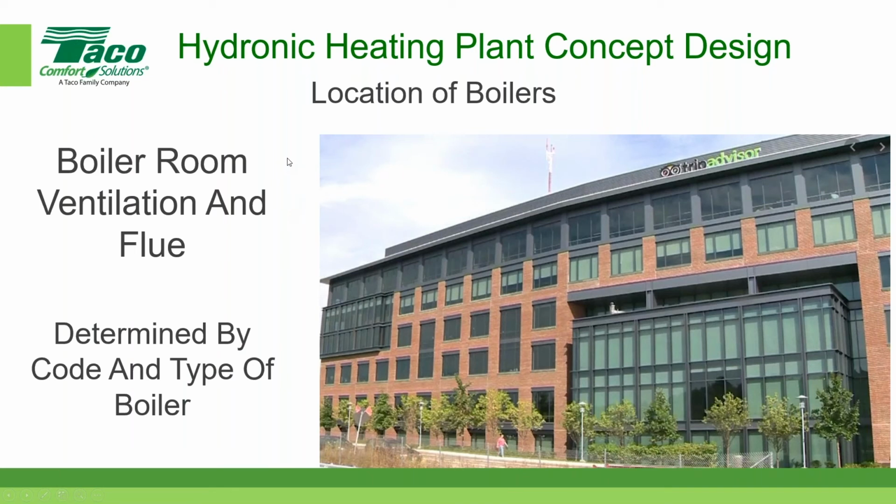The other thing I like to put in there is that the boiler room ventilation and flue has to be determined by the code and type of boilers that you have. So what do I mean by ventilation? Well, specifically, there are codes that govern how to ventilate a mechanical room if you're using natural gas as a fuel, if you're using fuel oil as a fuel, or propane as a fuel. And again, you have to check with your national and local codes to see precisely what they need for ventilation.